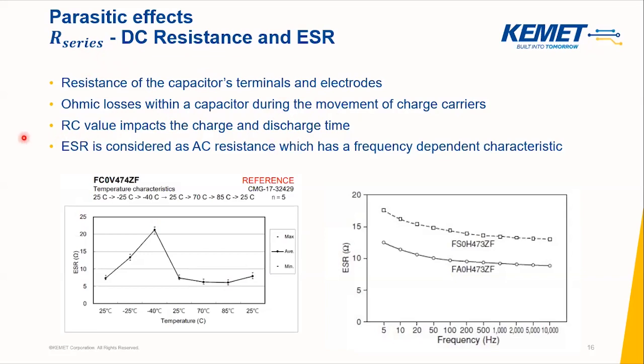And actually the multiplication of this resistance and the capacitance value impacts the charging and discharging time. Because of that, it is also an important parasitic effect that you need to consider when you are calculating the right capacitor for your application.